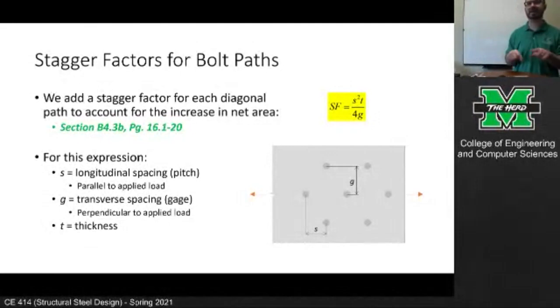So if the load is going left to right, S is your left to right dimension, G is your up and down dimension. G is perpendicular to the applied load, S is parallel to the applied load. That's the more general expression.